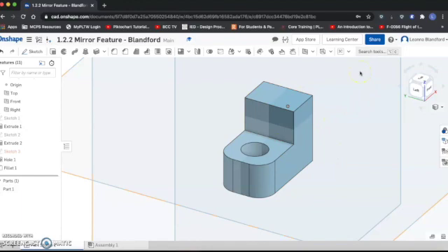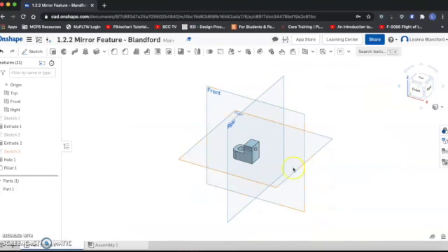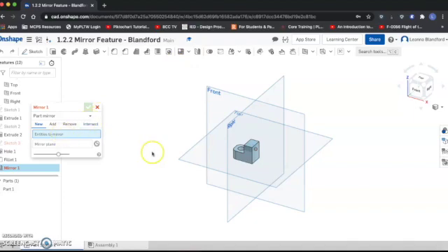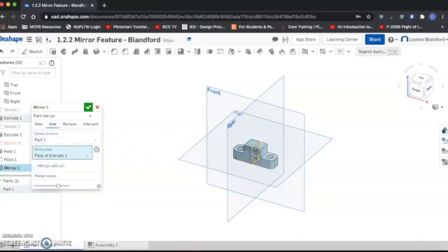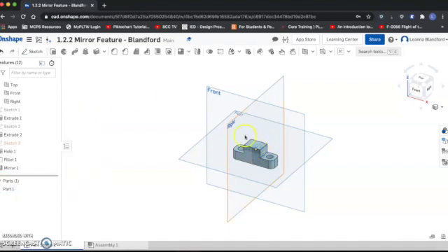If you bounce over to slide 45, it actually shows you that it wants you to mirror this to create another portion. So I am going to zip around to my front view and then I am going to grab my mirror tool and it says entities to mirror. So I'm going to click here and then my mirror plane, I am going to click here. And then I'm just going to hit that check mark and now it has created that entire surface.